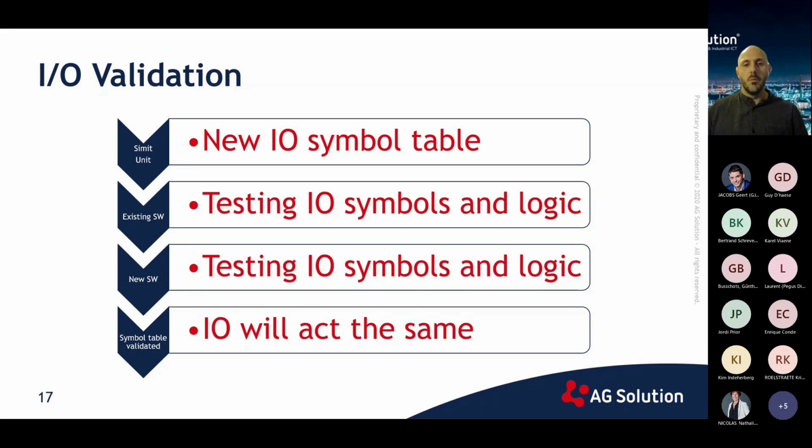The same testing routine will be performed. The application software will be modified where necessary so that in the end, all in and outputs behave the same. As the behavior will be identical and the fact that nothing will be changed in the field, remember, this is a software migration, we can state that there is no need for extensive in and output testing. Thus, the downtime due to this testing will be highly reduced.